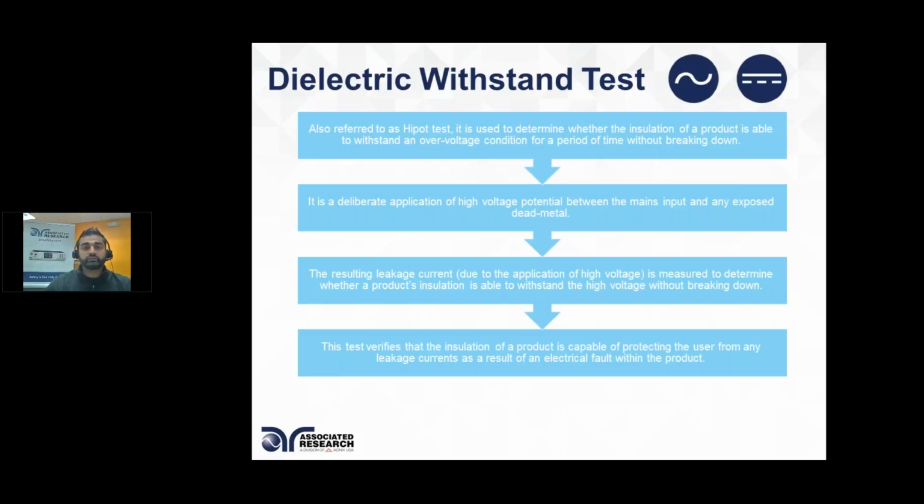So when they're switching at the utility station, there could be lightning strikes, or some other way some kind of transient made it onto the line and neutral of your product. At that point, if you design your product to only withstand around 230 volts, when those transients happen, and those transients could be anywhere from 1500 volts, 2000 volts, in that range, you're kind of creating a shock hazard for the end user.